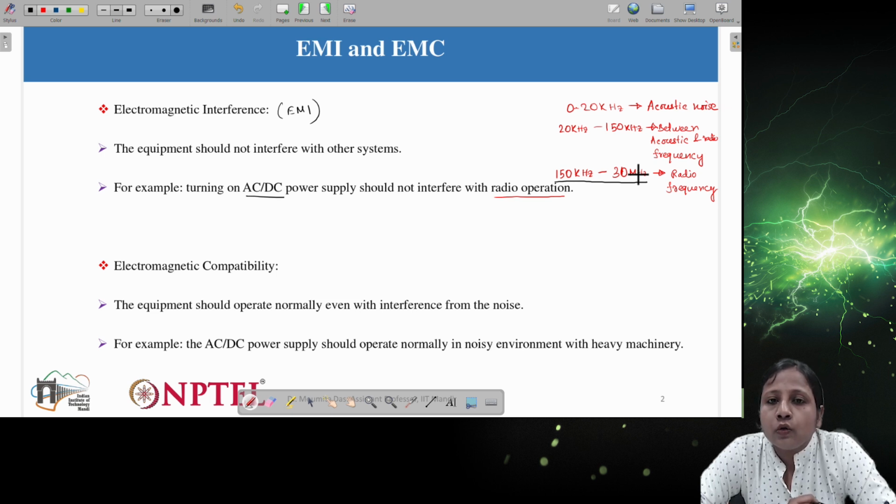But now, due to the introduction of wide bandgap devices in the power industry, this frequency level is increasing. We now expect the frequency of operation of wide bandgap devices, silicon carbide or gallium nitride, to be higher. For silicon carbide it will be around 150 or 200 kilohertz for high power applications, and for gallium nitride it is expected to be in megahertz.